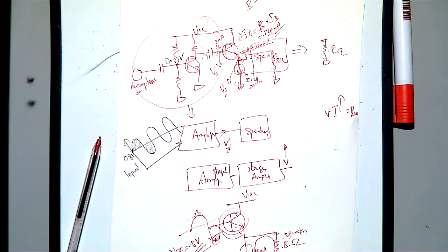And then since VB voltage is equal to VB1 plus VB2, a natural choice will be two diodes in series. And I1 in figure B, this one, is used to bias the diodes and Q1. So you can set this current, and then you can use these diodes, you can bias them, and also you can bias the Q1. So then if you do this, you don't have that dead zone problem. So now you don't have this issue. You will not lose anything here because this much is covered.